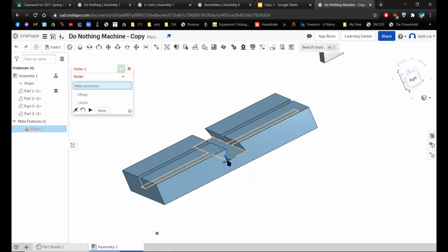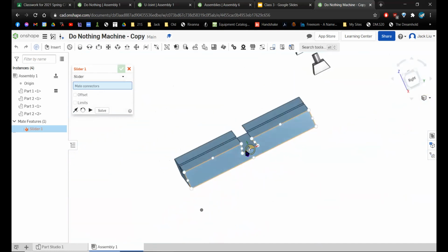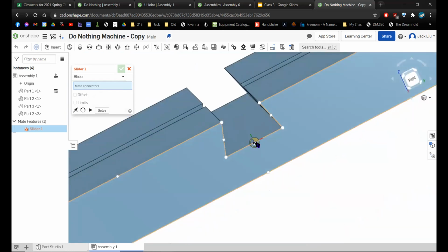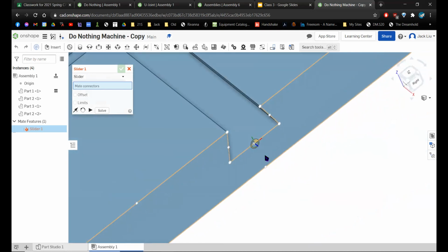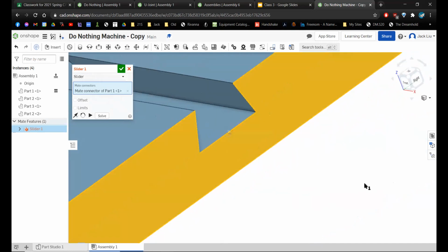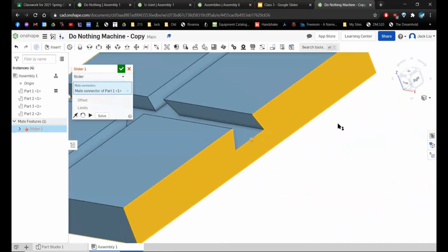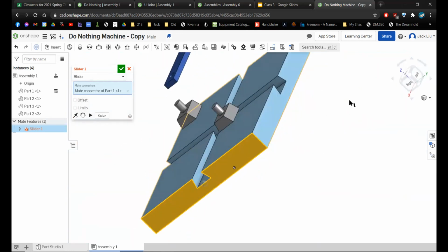So this yellow circle essentially is telling us which two positions are going to touch and move relative to each other. So the two positions I want to touch are kind of the bottom of my groove right here. Notice the blue is sticking out, the green is sticking up, and the red is sticking to the side. So I click once, and I've selected that position. You can see when I move my mouse away, it's still kind of there, just a little bit grayed out. So I've defined one point.